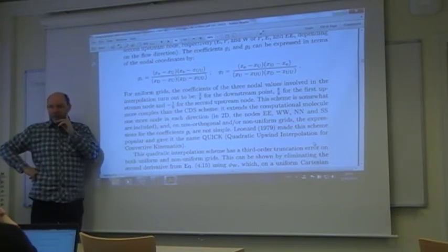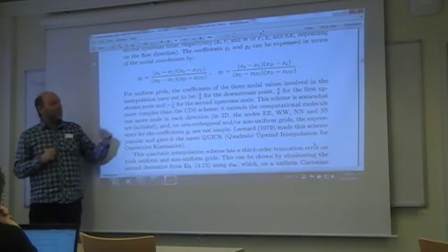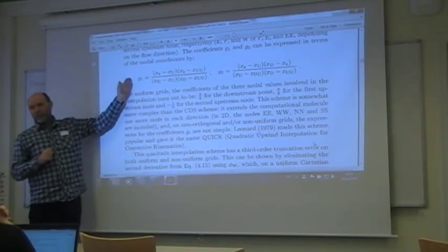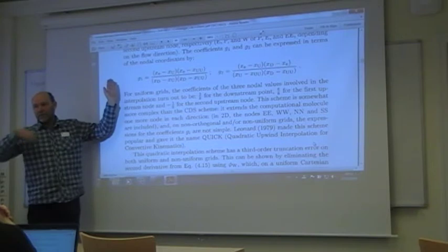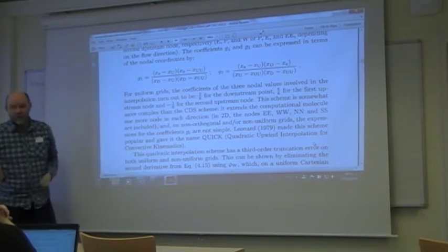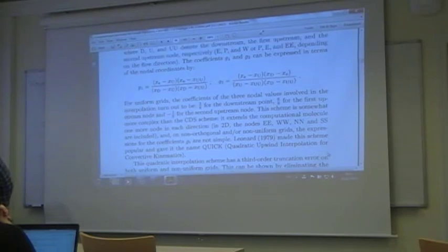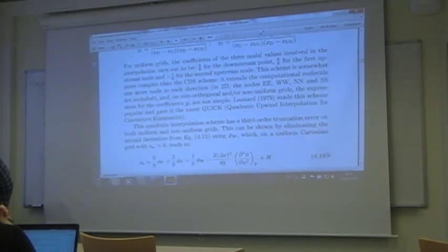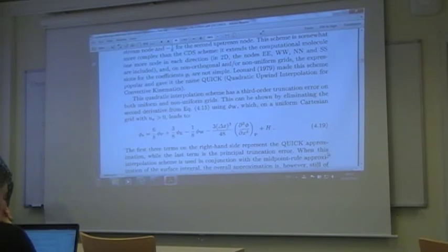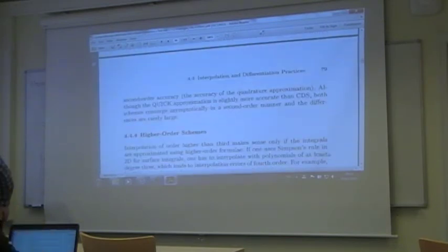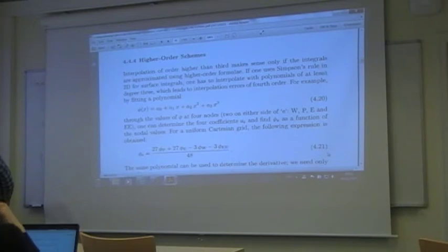And then when you have gotten the solution, you switch on more advanced schemes, and then you continue the simulation. So in that sense, these crude interpolation schemes, upwind schemes, are still valid to use. And you have, of course, also higher order schemes as well. But they can be tricky to use. I'll come back to that a little bit later also.